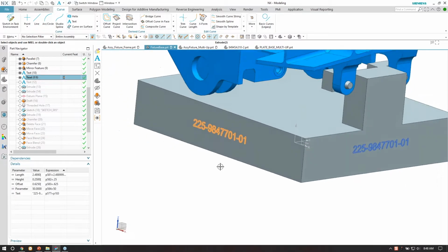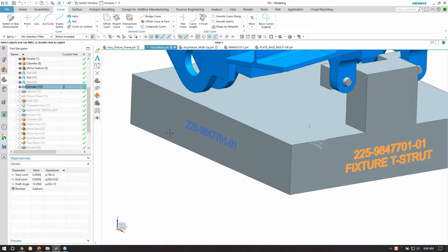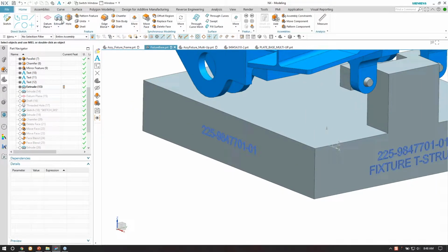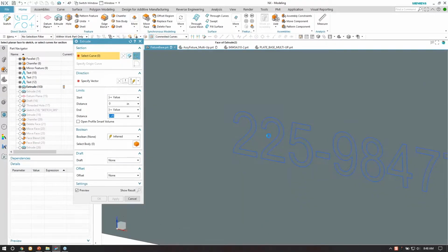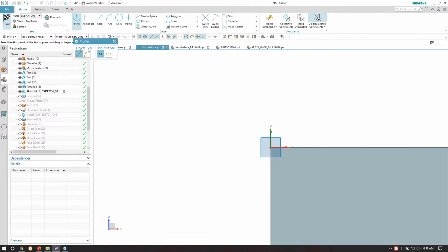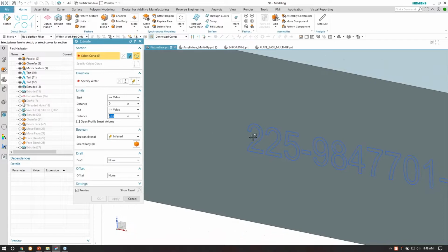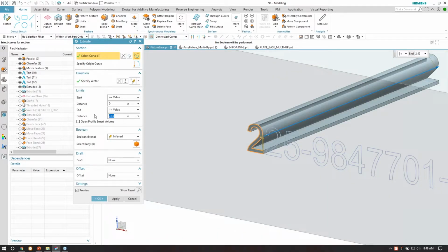Okay, if I continue to walk through the end of my part, bring it down here to this extrude. The extrude is created, and this is where it kind of gets a little bit important about how you pick your geometry. If I use an extrude here, and I just pick, say, connected curves and go through and grab, oops, I ended up picking the face instead of the curve itself. I'll get that curve there. Probably don't need it to be quite that big.